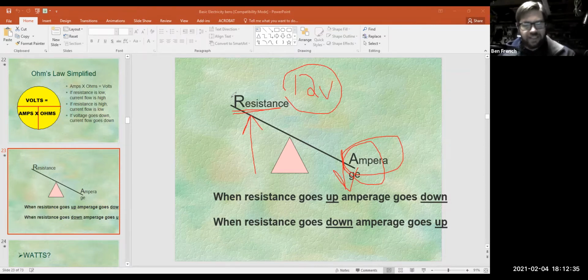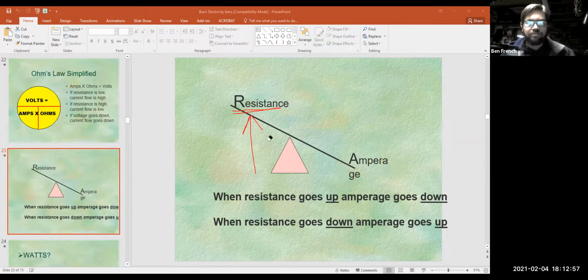If the device is maybe an electric motor or a headlight or a relay, that's where the resistance is supposed to be. It shouldn't be in the wires that connect to our components, right? We want our wires and our electrical connections to be relatively resistance free, so that our current can really do its work in the components.